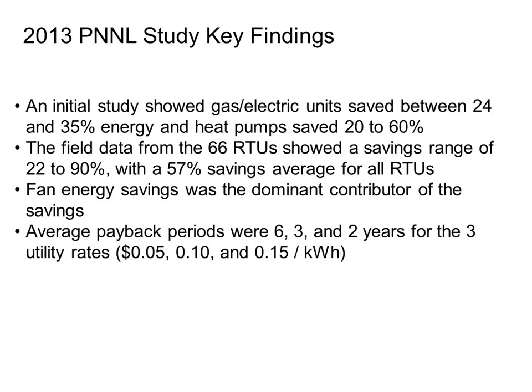The paybacks really depend on the utility costs and utility rebates, right? So the higher the utility cost, the faster the payback. Well, that's not surprising, obviously. And then the lower the utility rates, the longer your payback. So if you have a 10-cent kilowatt-hour electric rate like we have in many of the areas here in the Midwest, you're talking about a 3-year payback. If your rate's a little bit higher, more towards the 15-cent range, could be a 2-year payback for retrofitting some of these technologies. And then obviously if you have really cheap electricity, then the paybacks can be much longer.